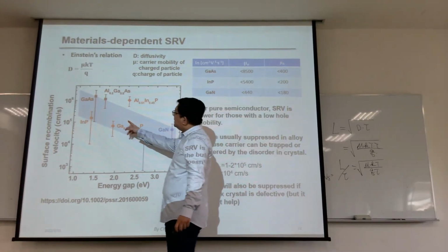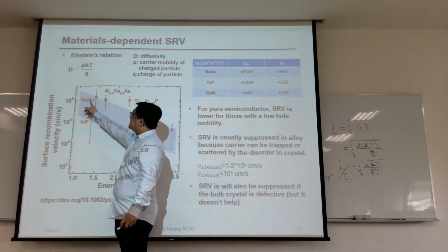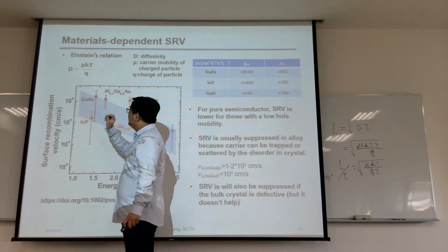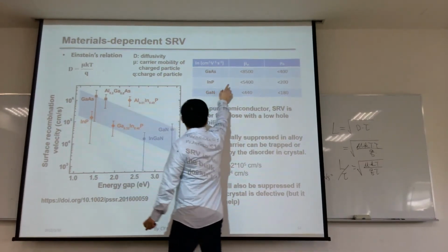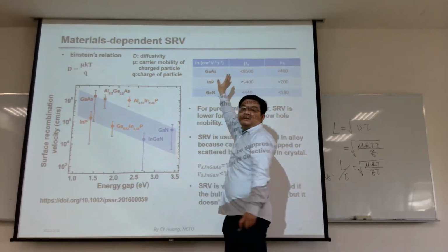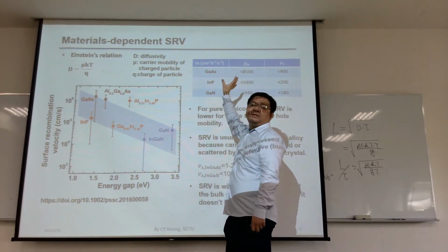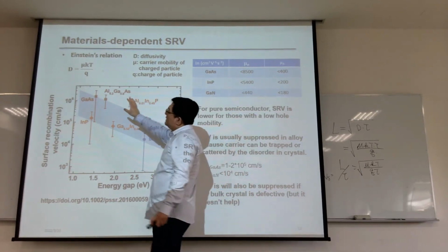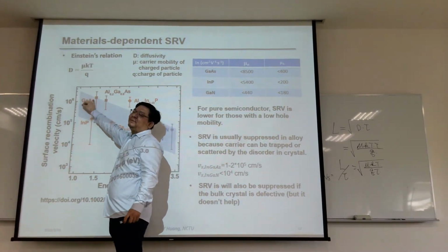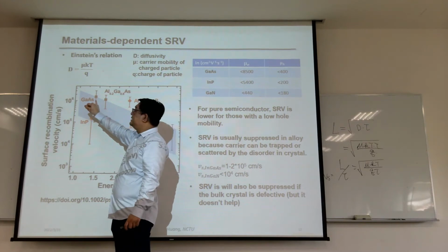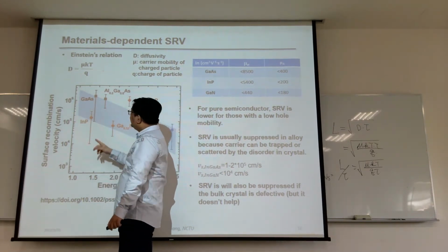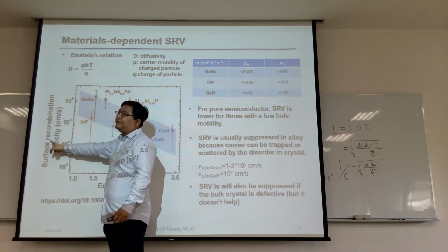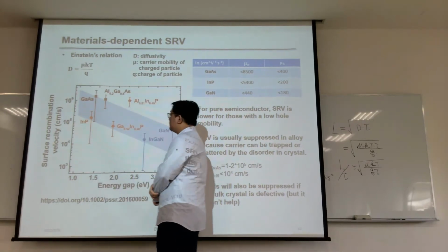On the other side, you see gallium arsenide has really good carrier mobility. That's how your cell phone operates with such high speed. But there's a problem: if you make a device very small, you have a very high surface recombination issue.